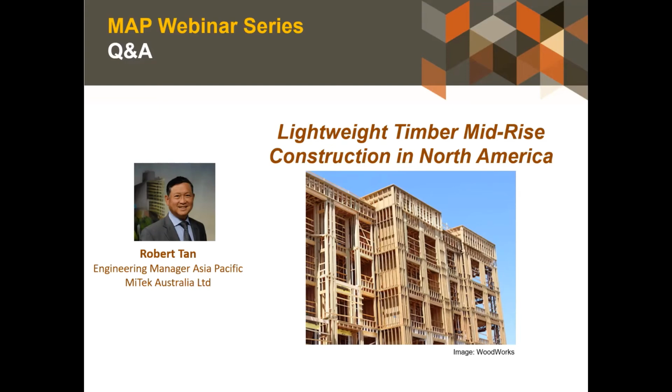Plywood was very common because it's just very easy to work around the whole building, create a constant cover over there. In terms of the structural steel, very rarely do we see structural steel bracing. It's only for very specific purposes if they have certain criteria to meet, such as in that particular brick building, which was designed to be brick clad, where they need a certain ductility or rigidity as the case may be, so that was done in that fashion. What other bracing system did I encounter over there? I think those were the three I talked about.